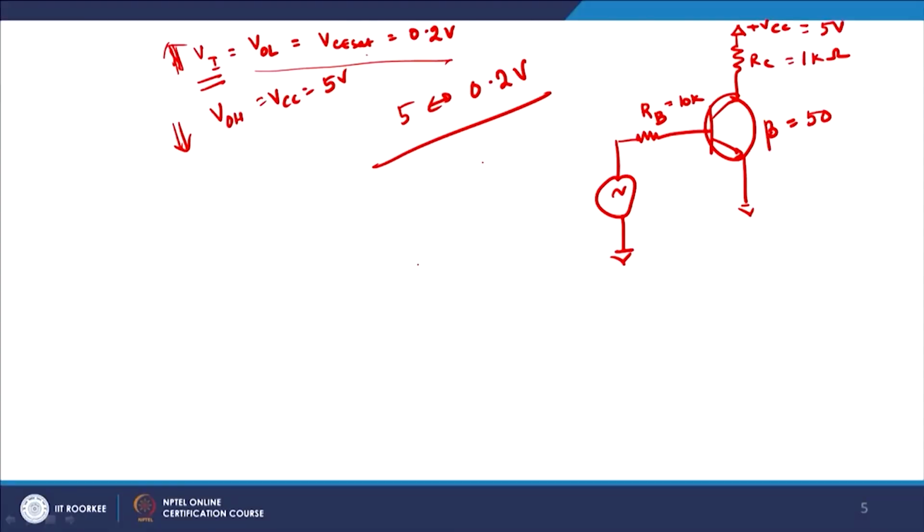This is the swing in the voltage domain which you see when you have such a system available. Now, let us assume that my Vin, or input, is between VIL, input low, and VIH. So, I am in the active region of operation.